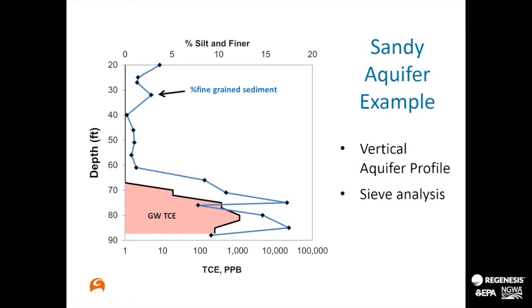It's just that the material up above has extremely high hydraulic conductivity, some of it, like I mentioned, pushing toward a centimeter per second. But look at where the TCE is. It's in the interbedded zone where we've got slightly more silt and finer material and slower velocities.